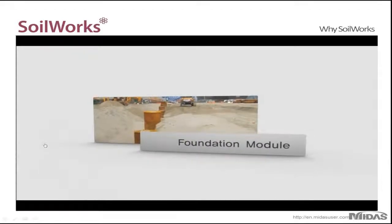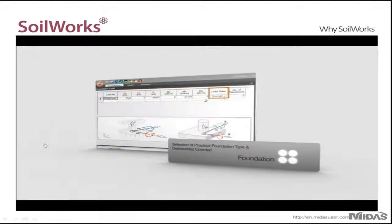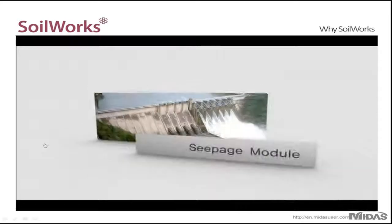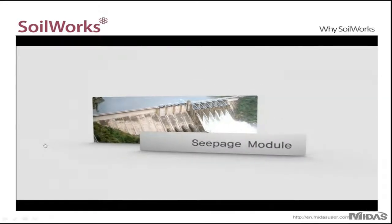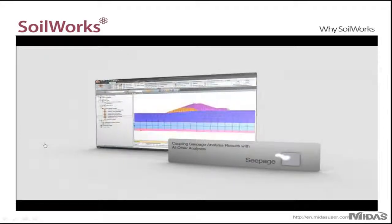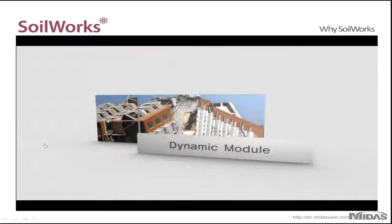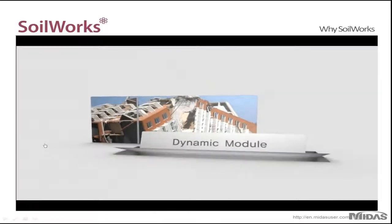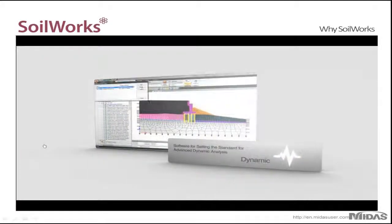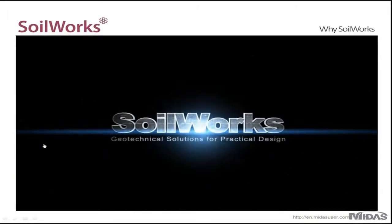Then there's the foundation module for a PY analysis of your pile configurations. So you can model and analyze multiple pile configurations simultaneously. And then there's the seepage module to analyze the effects of seepage on soil interaction. This is typically used for dams or levees, but it can also be used in coupled analysis with your slope module. And then last there's a dynamic module for seismic analysis. The software has a very in-depth database of time history records for earthquakes, so you can get a very accurate simulation of an earthquake in the area in which your project resides.